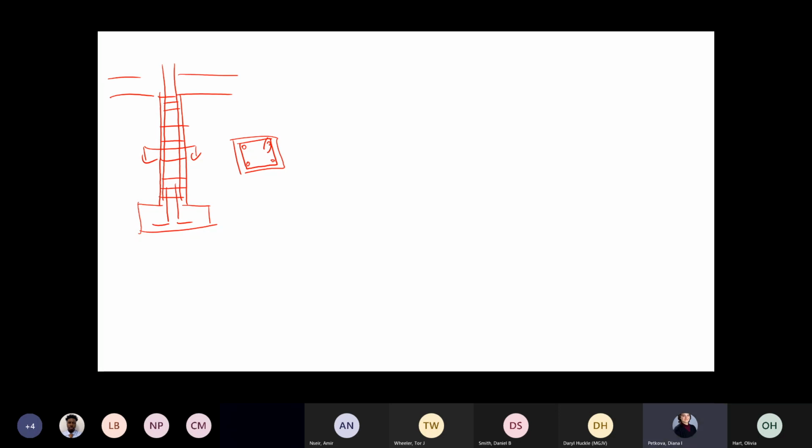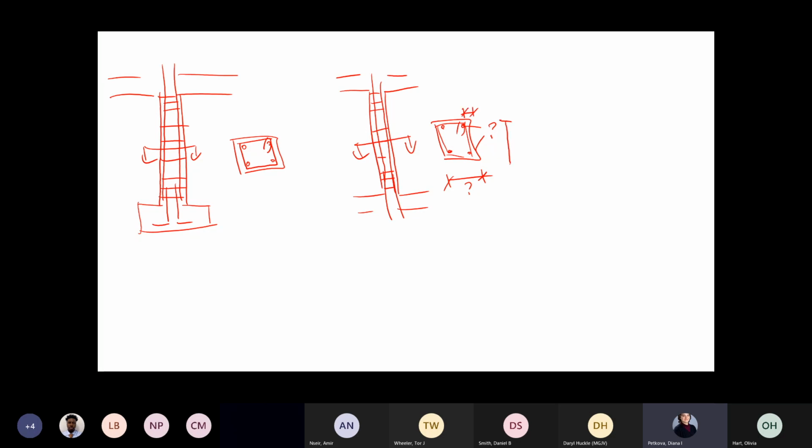Okay. So I think this is okay for the other level. Of course, we have the bars coming from the previous level. We have our bars. We have the links again. This is just to indicate that you have S and S reduced. Again, cross section. And of course, you need to give some detail here about what kind of bars you're using, the dimensions of the column, perhaps the D2 value. So these are the standard things which will just show your design.